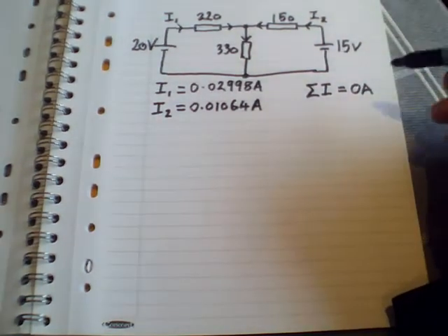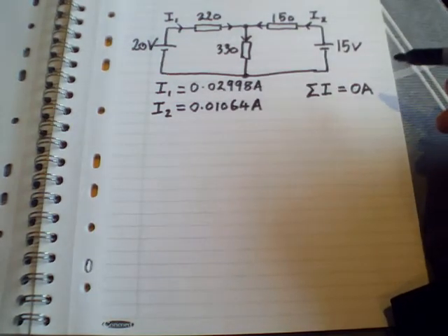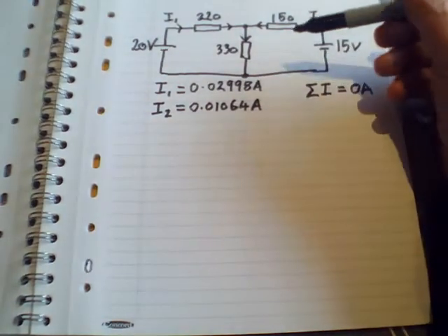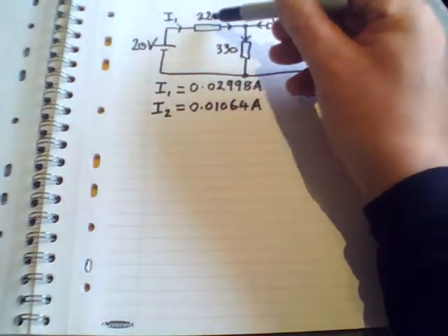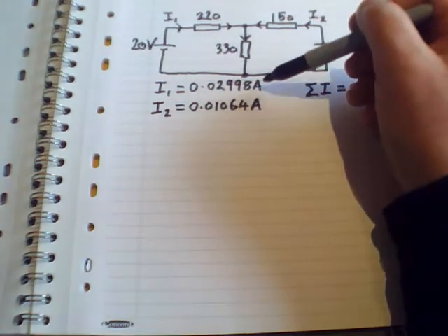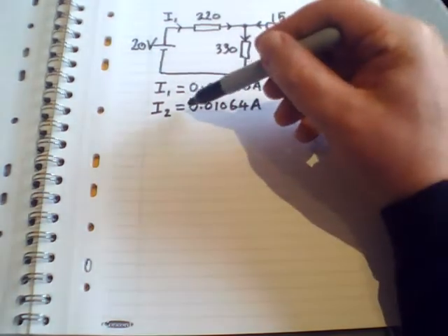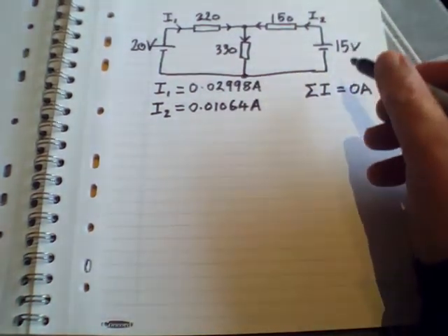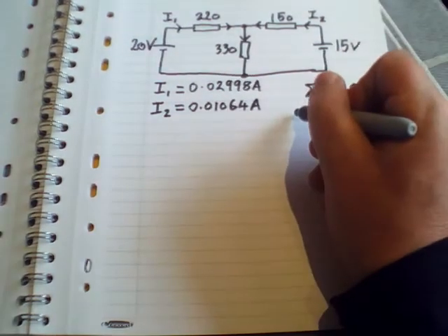Okay, so for the final part of this problem we've been working through, we've already calculated using Kirchhoff's voltage law, Ohm's law, and simultaneous equations that the current in this part of the circuit here, I1, is 0.02998 amps, and the current I2 in this part of the circuit is 0.01064 amps. So we're going to make use of Kirchhoff's current law now, which basically says that